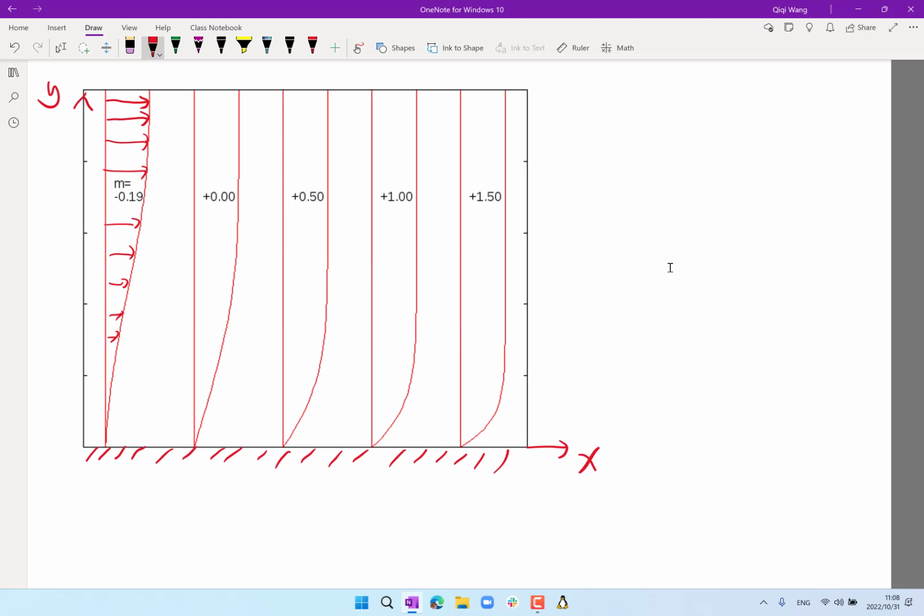So usually the resulting velocity profile in a boundary layer is really a smooth function like what you are seeing here. Whatever quantity we use to characterize a boundary layer has to take into account that the velocity changes very smoothly as a function of the distance from the wall.